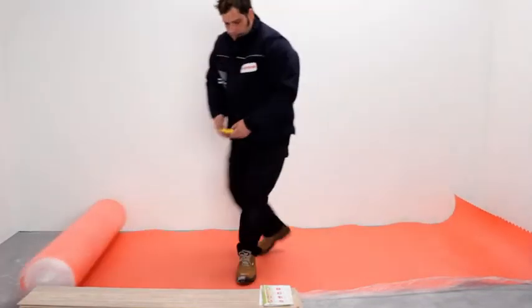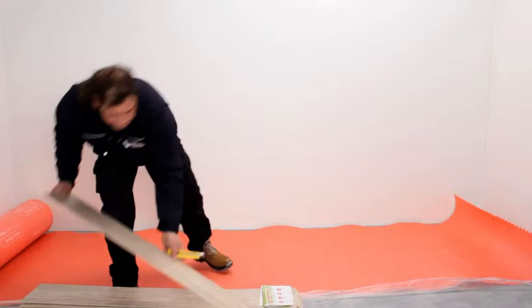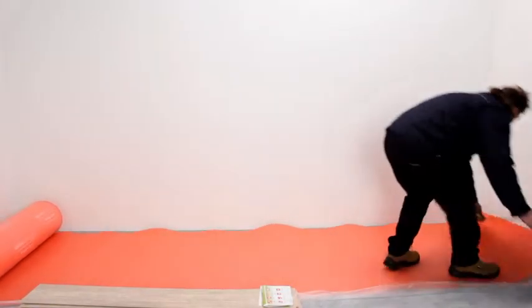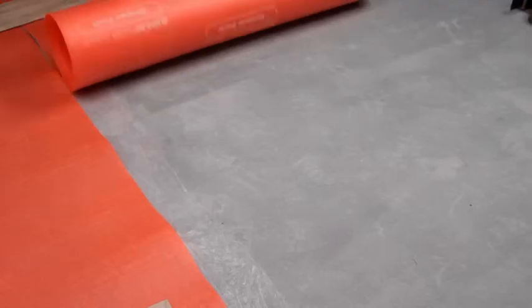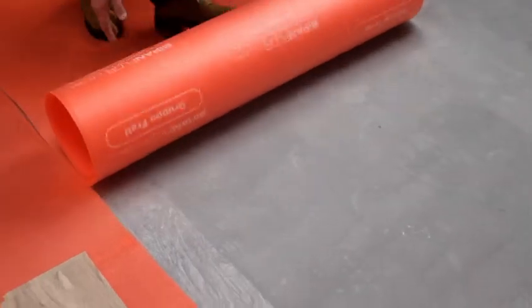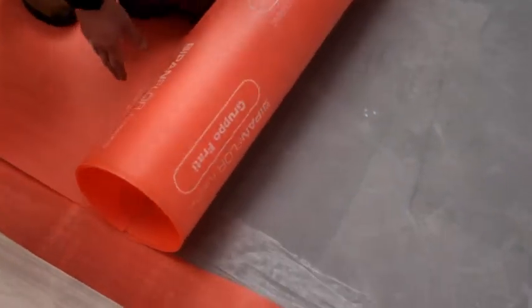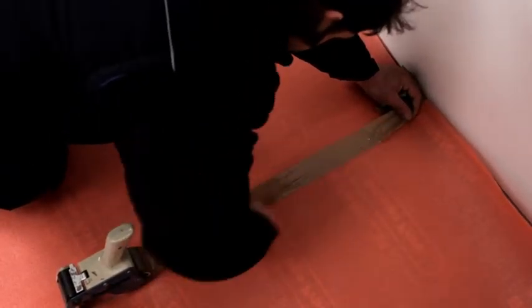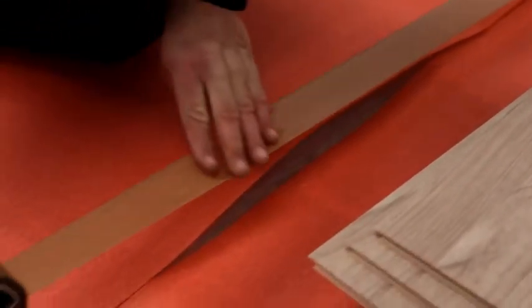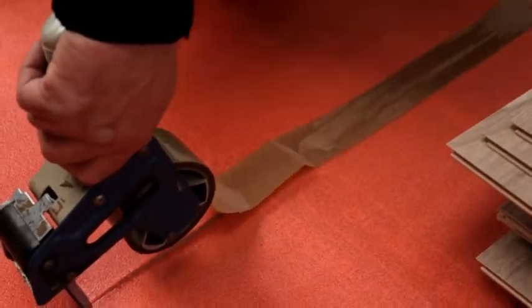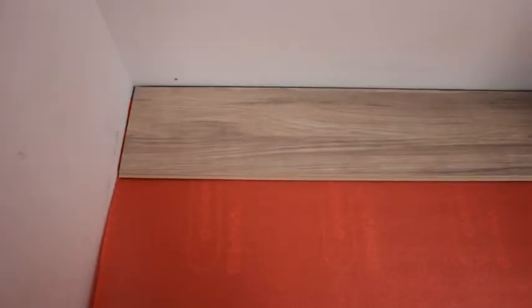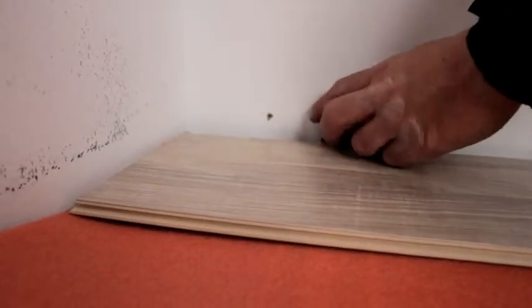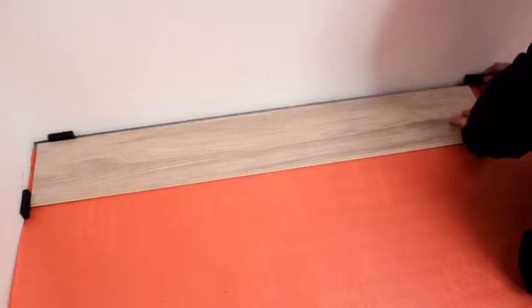First of all, lay the underfloor with the nylon side turned downwards. Lay alongside the following underfloor strip, overlapping it to the nylon. Secure the joint by means of the PVC tape. Position the first row of slats with the female joint turned towards the wall, keeping it to the wall with the spacing wedges.